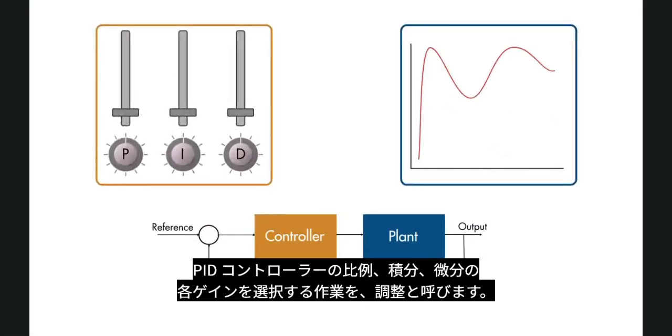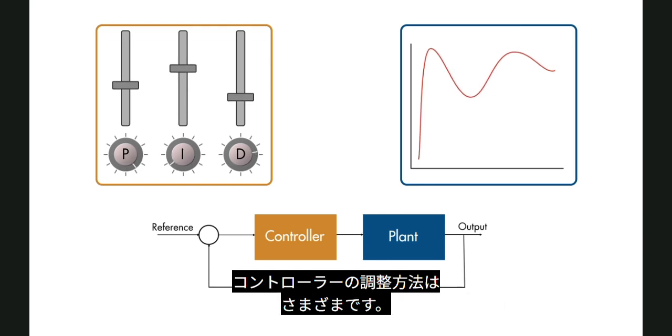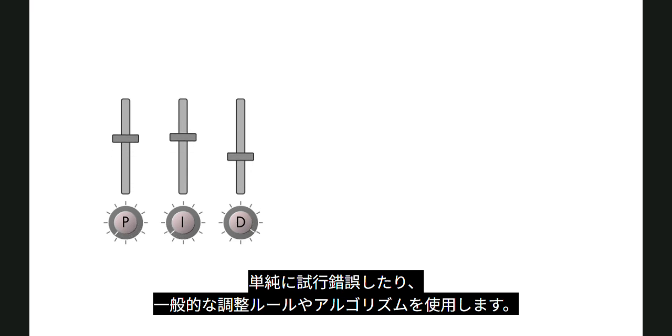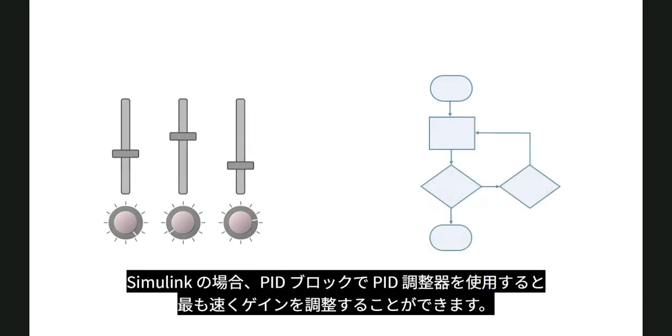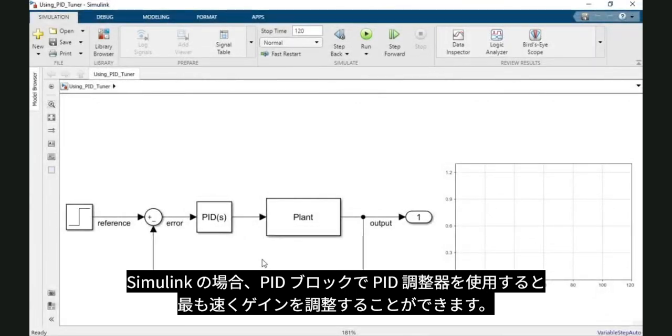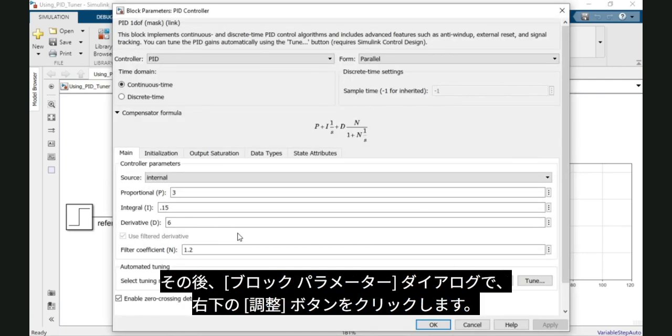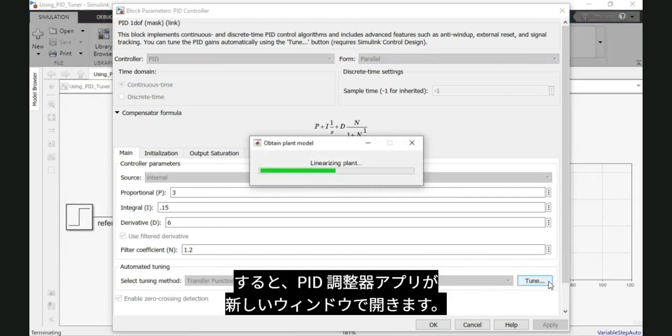Choosing the proportional, integral, and derivative gains for a controller is called tuning the controller. There are different methods for tuning a controller. Some engineers simply use trial and error, while others use common tuning rules or algorithms. In Simulink, the fastest way to tune gains is to use the PID Tuner app, accessible directly from the PID block. To open the app, double-click on the PID block that you wish to tune. Then, from the Block Parameters dialog, click the Tune button in the lower right. The PID Tuner app will open in a new window.